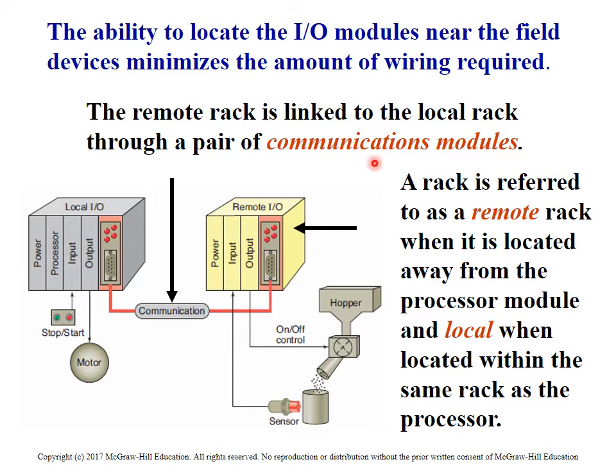Communication modules. Now, I mentioned that before. A lot of the new PLCs have a communication module that slides into them. Many of them have a communication module attached to the processor already, so they're able to communicate to other remote I/O, remote locations. In this particular example, they're actually showing an expansion rack, where an expansion rack is connected to the main rack, allowing it to have remote I/O.